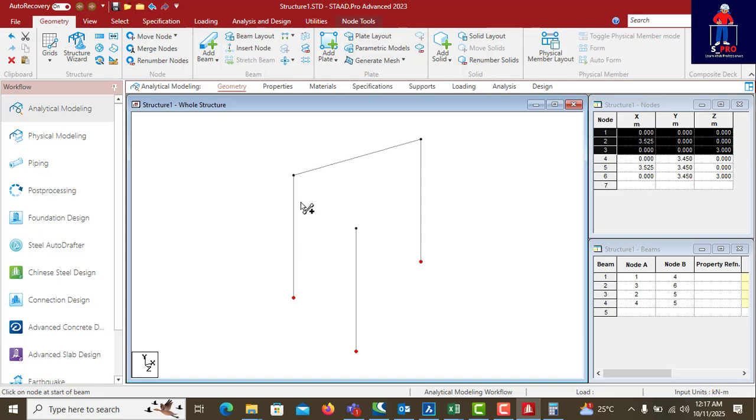I started from ground to top, from ground to top. You have to maintain that orientation because it's very important. So now when I'm putting the beams, I try to make them come from the point of origin to the other point. This point is my origin. So if I want to create this beam now, I'll come this way to this point, not from here to there. So these are also very important. It helps to align your beam orientation.